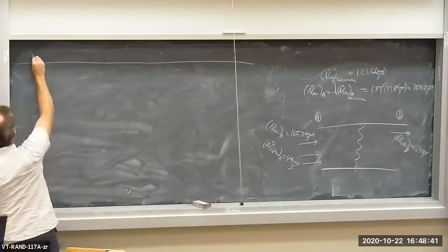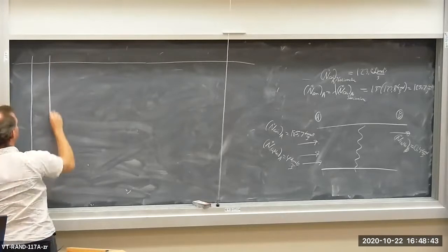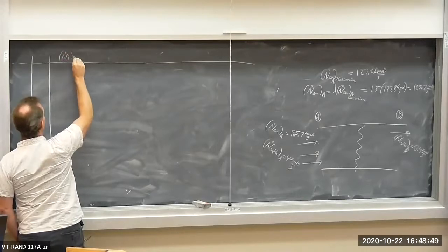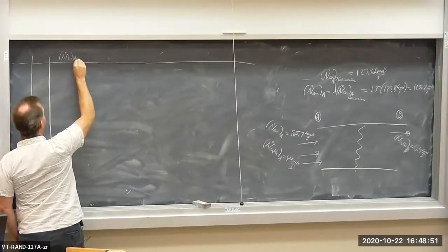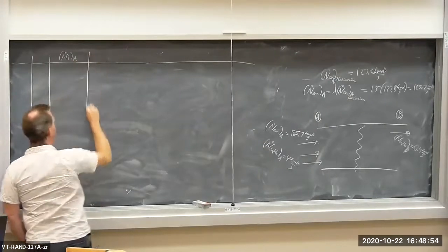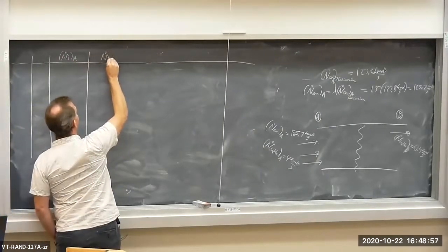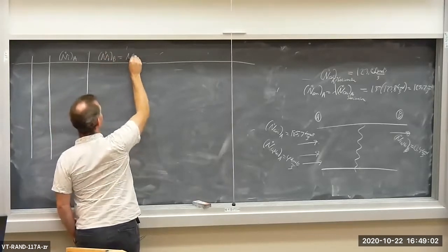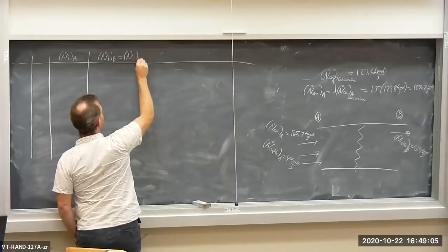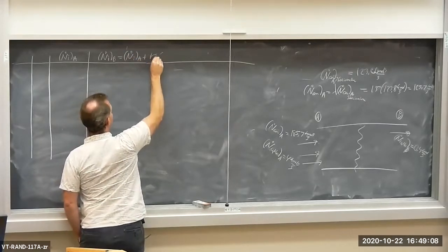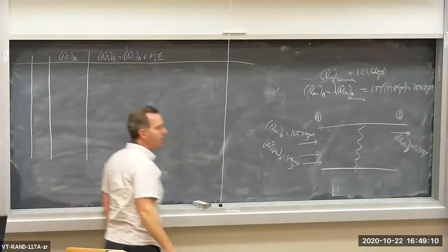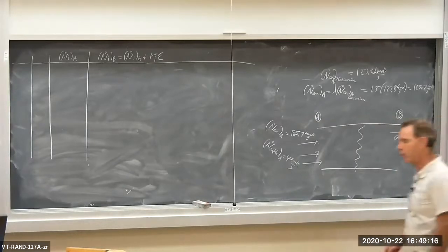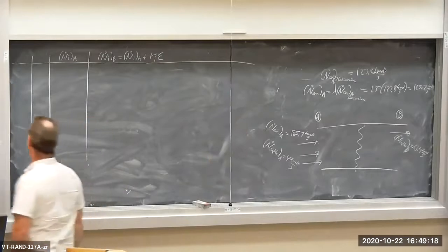Hopefully we'll have enough room here. So we have the component stoichiometric coefficient, n dot i, the component flow rate at the inlet on the reactant side. And then n dot i, the mole flow rate on the product side, is equal to the mole flow rate on the reactant side plus the stoichiometric coefficient times the reaction coordinate, epsilon. Our flow rates are all different now, so the reaction coordinate is going to be different than when we did the previous example. You'll see this.